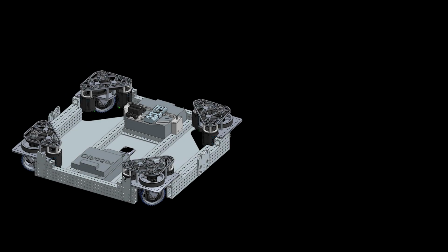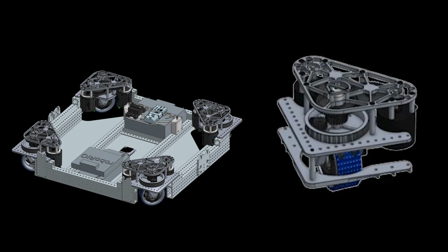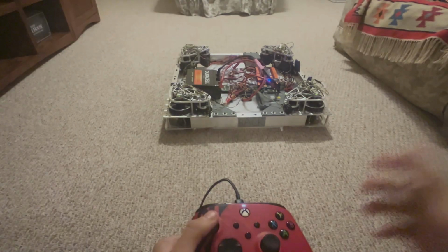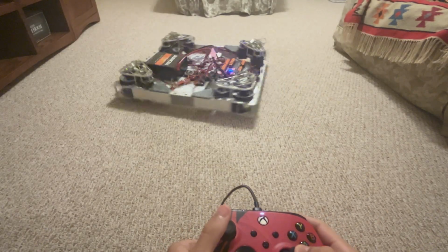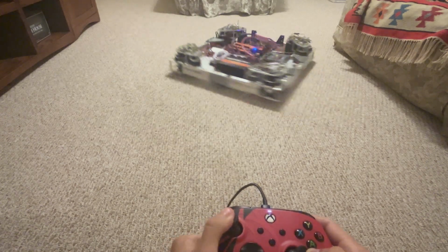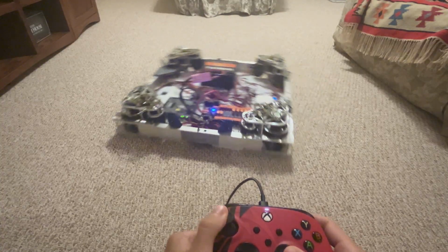Swerve drives are made up of 4 Swerve modules, one module for each corner of the robot. Each module has a driving motor and a steering motor. The reason Swerve drives are so good is because in this configuration, each wheel can steer independently while maintaining full power. With some fancy code, we can get our robot to move in any direction, turn in place, and even turn while moving. Swerve drives offer complete freedom of motion, and it is our job as programmers to realize it.